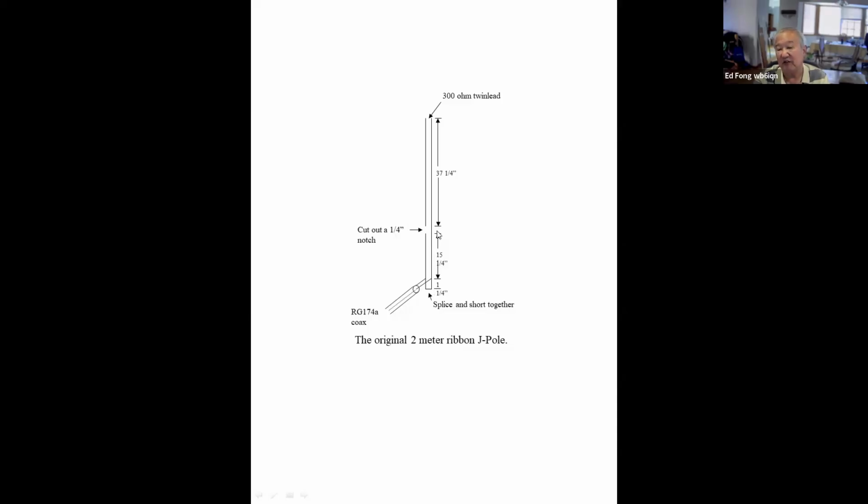This is just basically an end-fed VHF antenna. No different than these end-fed HF antennas. You usually need some matching element down here. At VHF, you can put a quarter wave stub because it's only 16 and a half inches. At HF, you use the 49 to 1 transformer. And that tends to be lossy, but it's better than nothing. And it's hard to do this at UHF because, again, you use that toroid. You can't do a transformer like that at UHF. You need to use a quarter wave stub like this. So it's 0 ohms here. It's a high impedance there. End-fed matches. You tap it off at about 1¼ inches or so, and you get about 50 ohms.